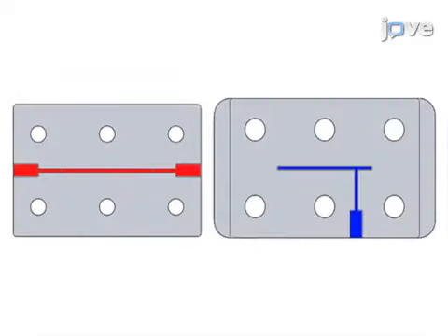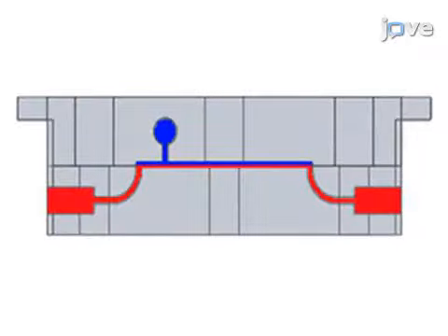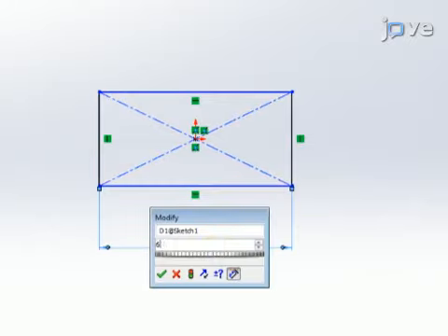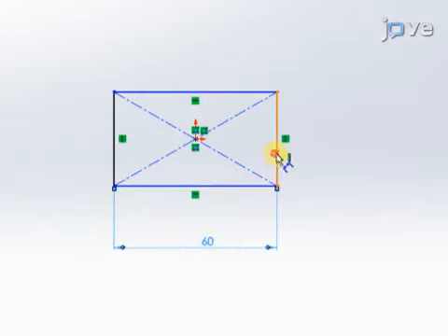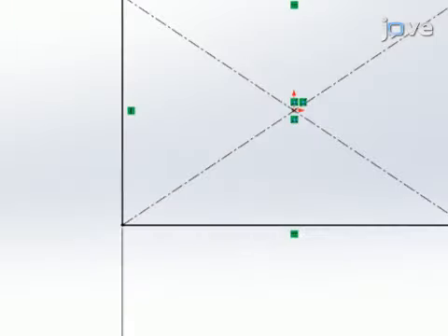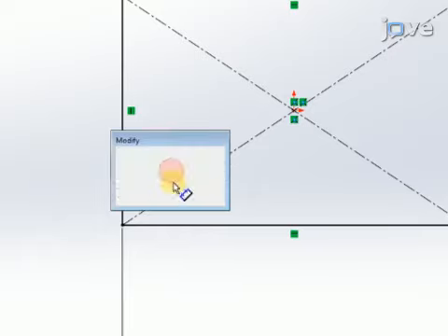Begin by designing the microfluidic device in 2 separate parts using a computer-aided drafting program. To make the bottom layer, use the rectangle tool to draw a 40 mm by 60 mm rectangle. At one corner of the rectangle, use the circle tool to create a 6.2 mm diameter circle.